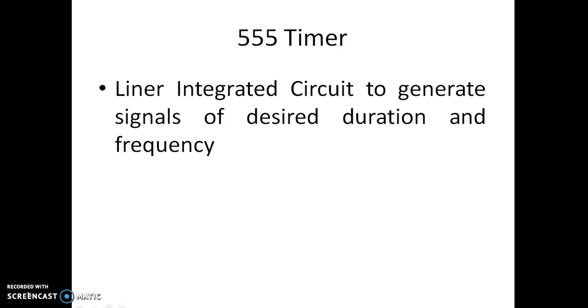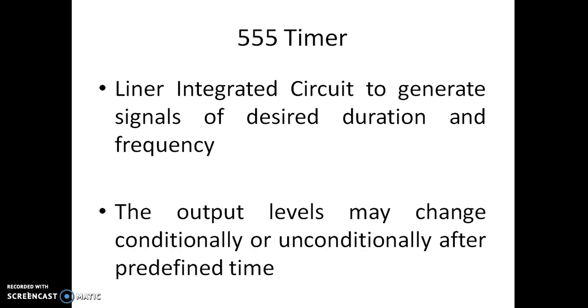Now let us first have a look at what a 555 Timer is. The 555 Timer is a linear integrated circuit. It is used to generate signals of desired duration and frequency. So you can design it for any particular duration, on and off time, and whatever frequency you want to generate. The output levels may change conditionally or unconditionally after the predefined time.